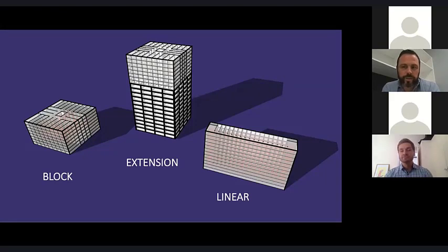Yeah, and with that, from a buildability perspective, and we'll talk about this in more detail later on in the presentation, is the need for hybrid design and construction approaches. So it's really great, but not enormously common to have a pure timber building like the block formation that Nathan shows on the screen here, where you can have a timber core and the ability to manage those connections, manage all the materials and the interfaces, albeit timber, the differential settlement components of everything being very consistent.